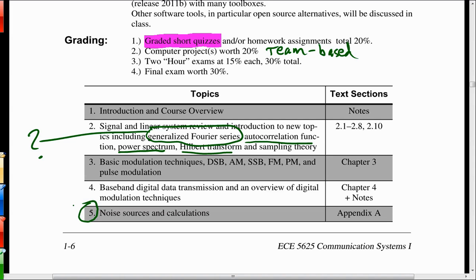Propagation and wave propagation is also something that falls sort of in the crack a little bit too. Communications engineers want to understand propagation theory, and I'll be getting into that in this intro chapter, because our communications waveforms rely on it, and we have to design our systems to account for that. If there's a heavy thunder shower going on and a SATCOM link is going through that thunder shower, do you think it goes through unimpaired? It doesn't. So the system has to be designed to tolerate things like that.